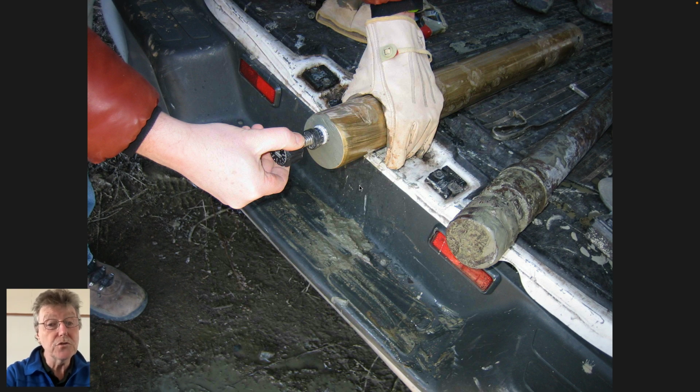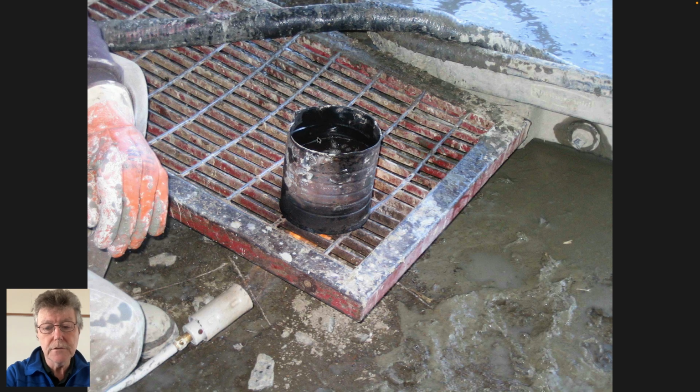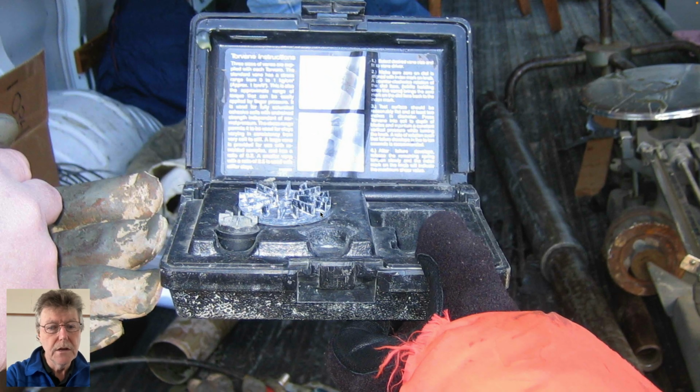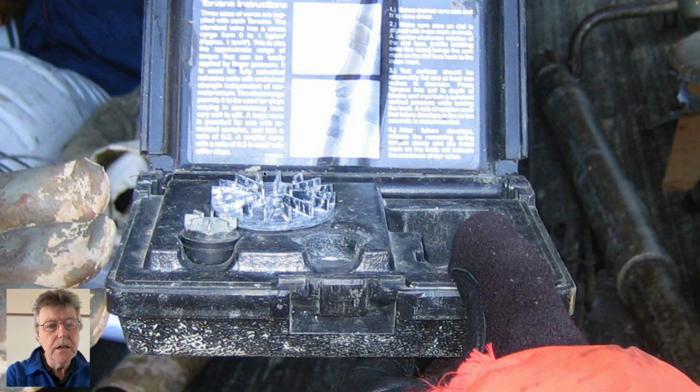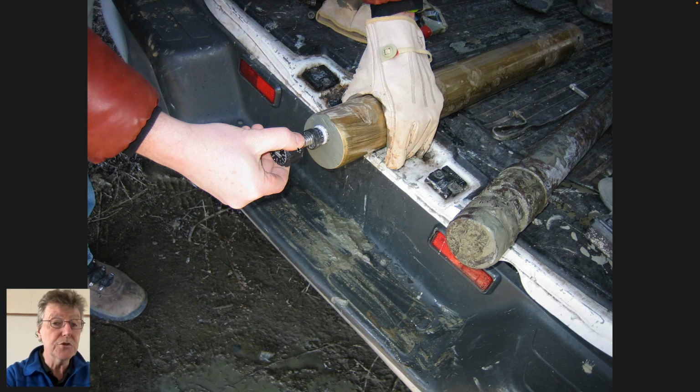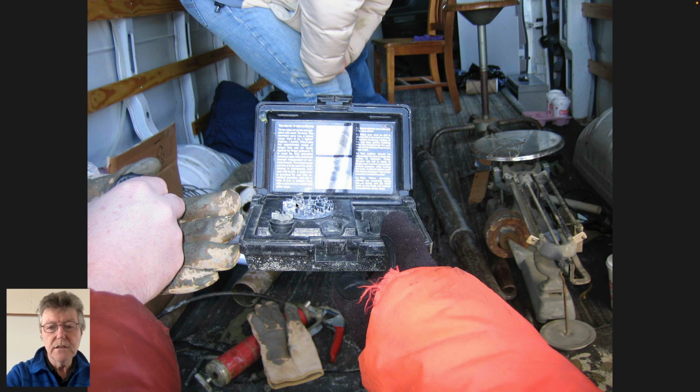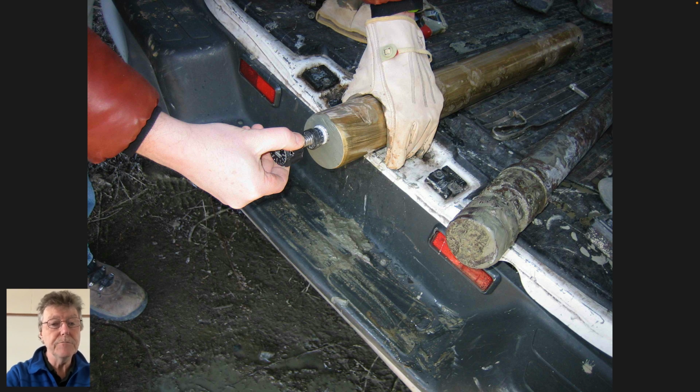If you want to, you can measure the strength of it with a Torvane. I think there's a picture of a Torvane. A Torvane is just a little wheel with these protrusions on it, almost like a mill wheel. You press that into the end of the sample with basically a torque wrench, something that you turn, and when it reaches the limiting strength of the soil, it fails. And so the soil allows these mill wheels to rotate, and at that point you know what the maximum strength of the soil is, just because of the torque that you've applied.